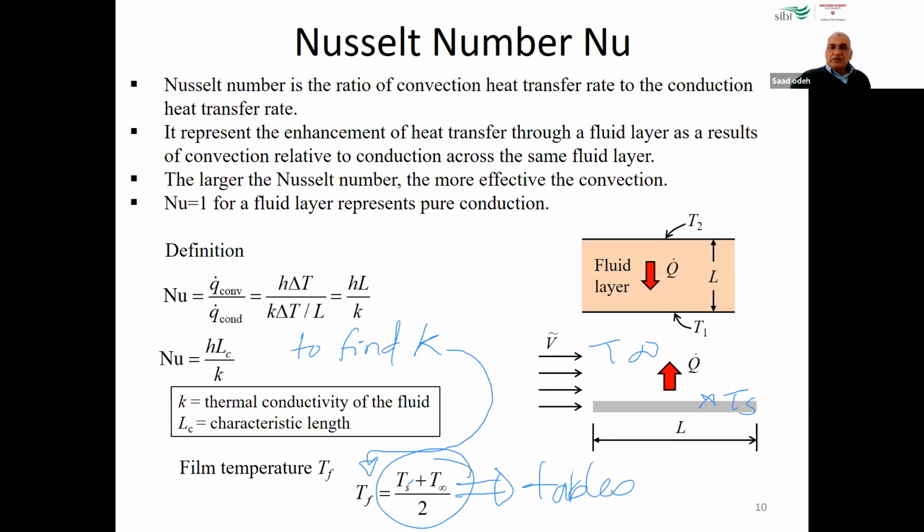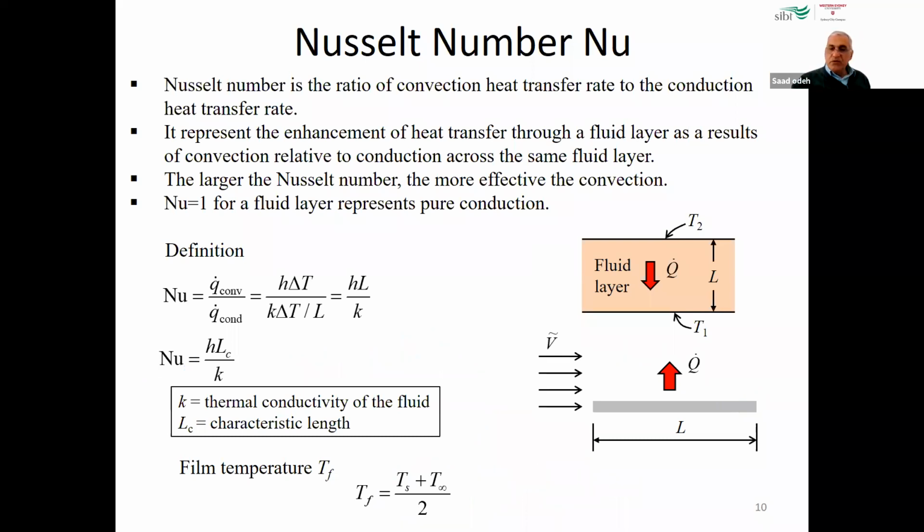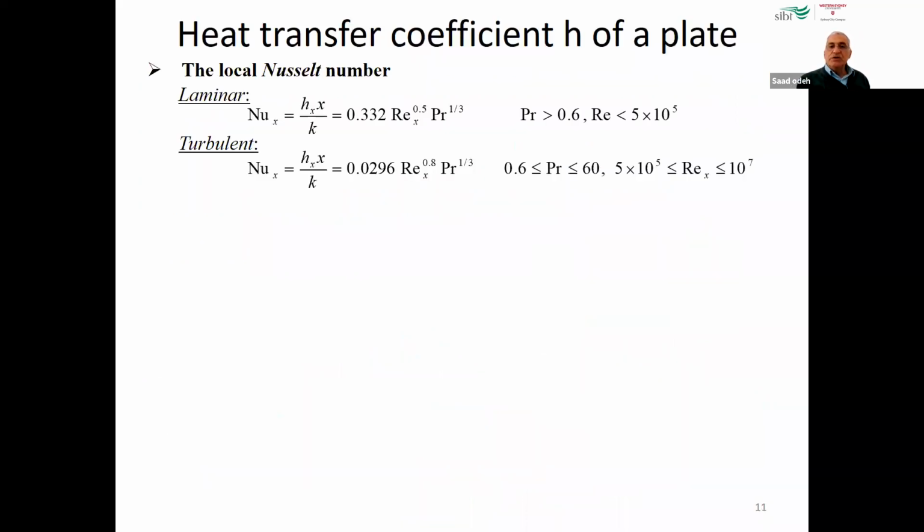All right. Okay. What else here? We have one thing left. We need to find the Nusselt number. Now, the Nusselt number follows different equations. We said before that based on the Reynolds number, or based on the type of flow, which is laminar flow or turbulent flow, we can find the Nusselt number.